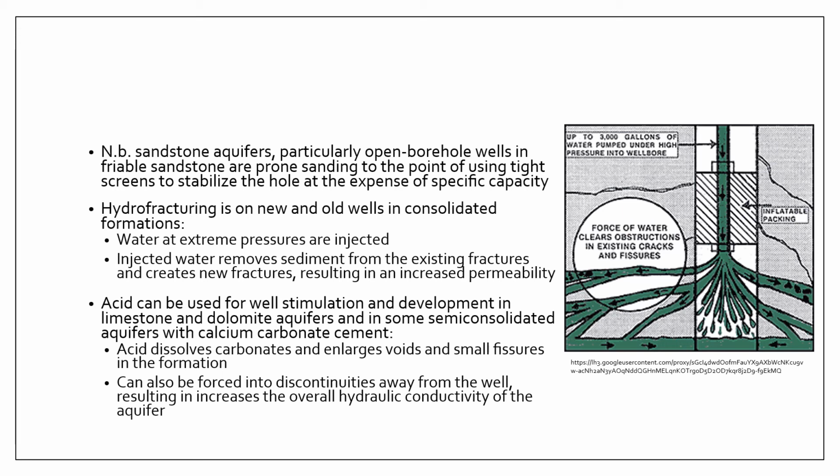All right. Now there are other considerations in well development. For example, sandstone aquifers can be quite problematic, especially if you're dealing with poorly cemented sandstone that are friable. All right. So friable sandstones are typically difficult to subject to water well development because they are prone to loosening.